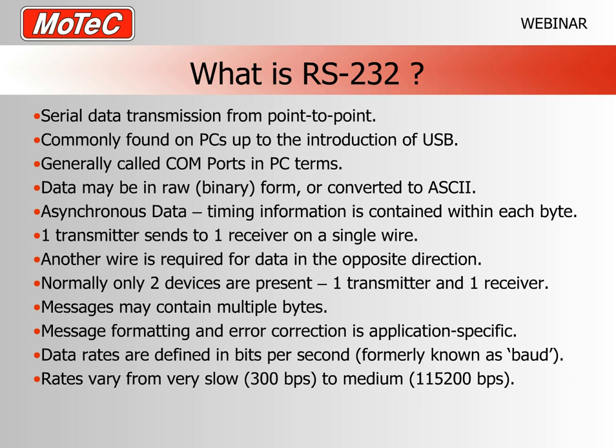Now, RS232 was designed initially for transmitting data to terminals, again in the early days of data communication, things like teletypes. And so there are two forms of data that are normally carried on RS232. Either binary data, which is what we would traditionally use in modern parlance, and the other type of data was a form of converting text data, which is called ASCII, the American Standard Code for Information Interchange, normally just called ASCII. Now, ASCII is often used for things like text. Typically, it's used for strings and messages like that.